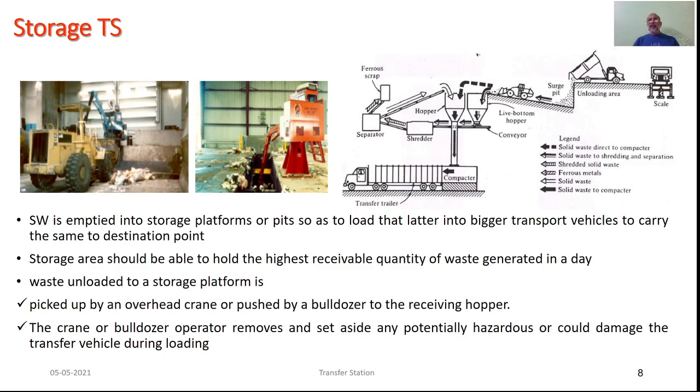This waste generation depends on so many parameters and it is a dynamic process. And as far as present trends are concerned, waste generation is going to increase in the coming years. That means one is expected to predict this waste generation, and for a certain design life, this particular area should be designed as well as acquired.